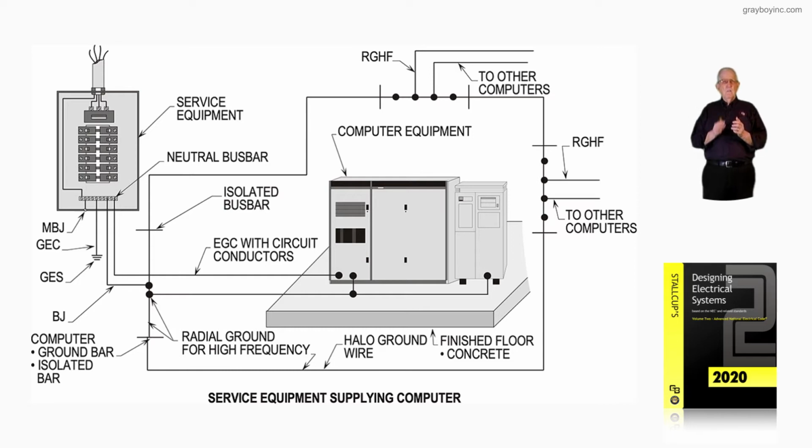Now, we've looked at the grounding electrode system, the grounding electrodes, so I won't bother you with that again. But now notice that spacer is placed right at the equipment to the right where we have the non-metallic spacer. Now it's put there for a reason. If the equipment is generating noise or any kind of magnetic electric field currents, the spacer will stop that current from flowing over the metal and raceway right there.